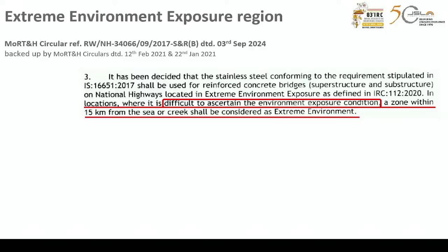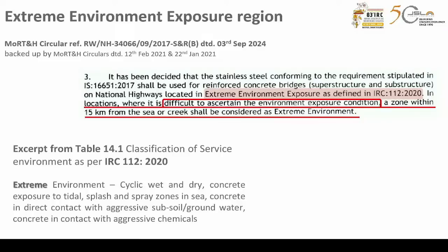But there is a section mentioned above, which is extreme environment exposure as defined in IRC 112. Now, if I refer to extreme environment exposure as per IRC 112, the definition in Table 14.1 says that it is a bridge which has cyclic wet and dry cycles, concrete exposed to tidal splash and spray zones in sea, concrete in direct contact with aggressive subsoil or groundwater, and concrete in contact with aggressive chemicals.